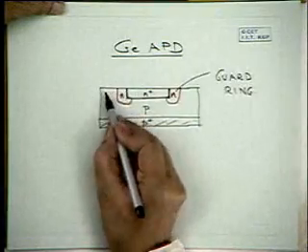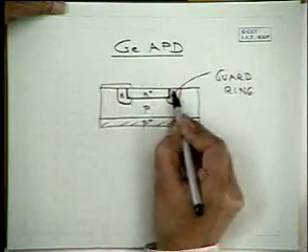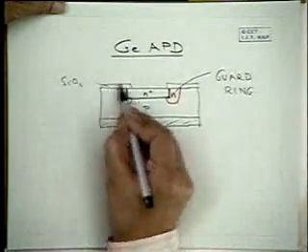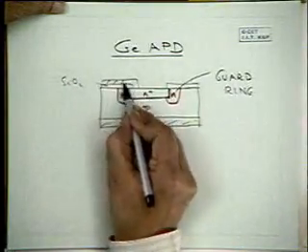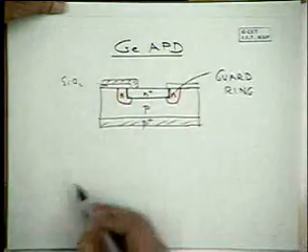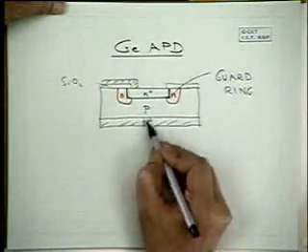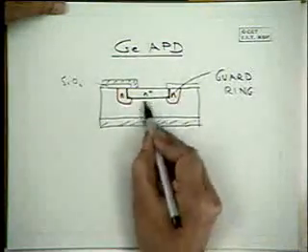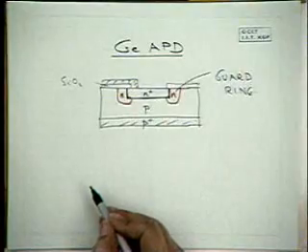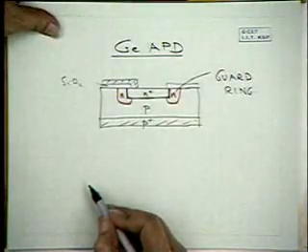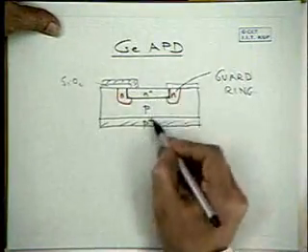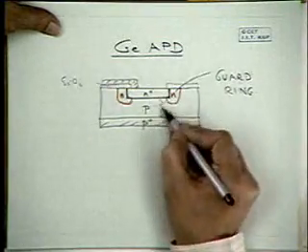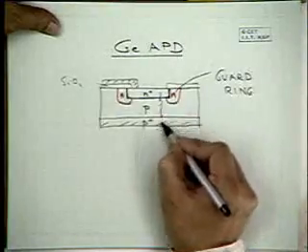And the rest of it is just a dielectric, say SiO2 passivation, and then you have some metal contact. Because it works at high field, the material itself has to be very pure, very high quality, without any dislocations or edge pit densities, so that there should not be breakdown. You should not have a little microplasma breakdown between here and here, or across.